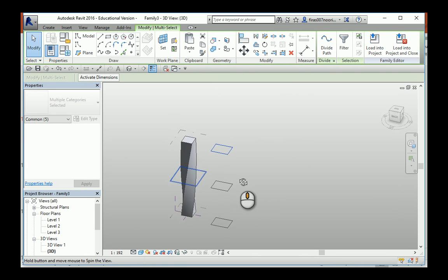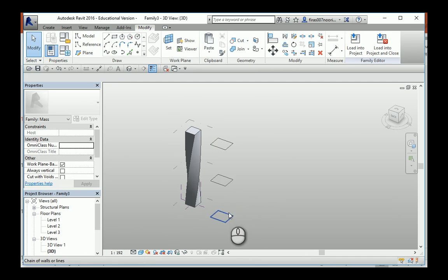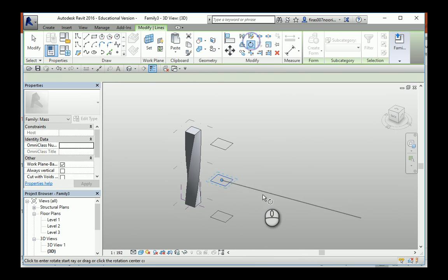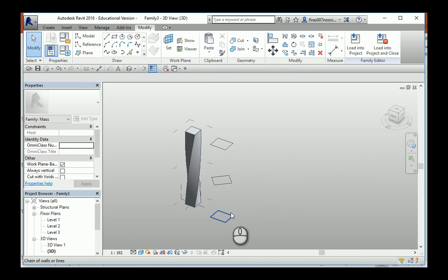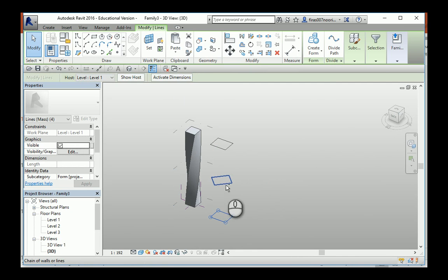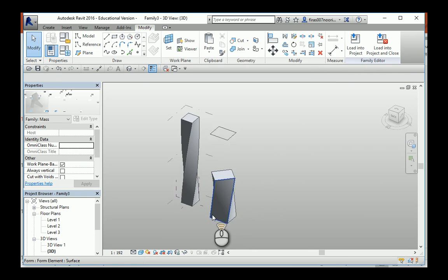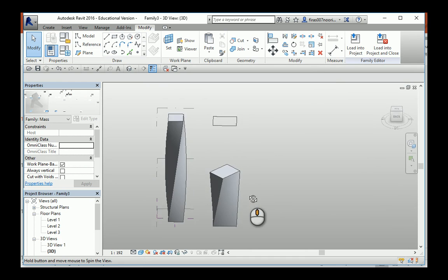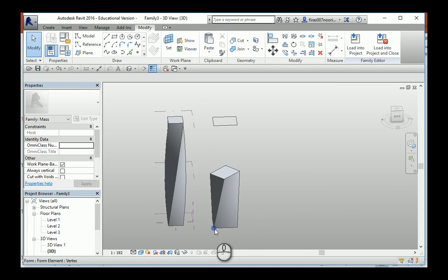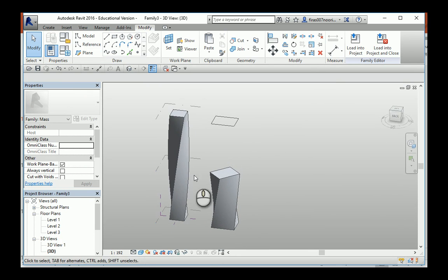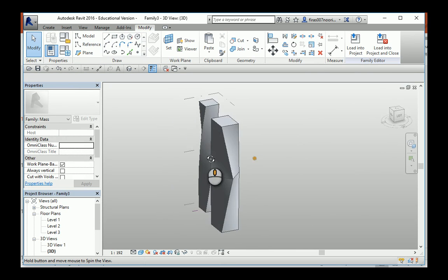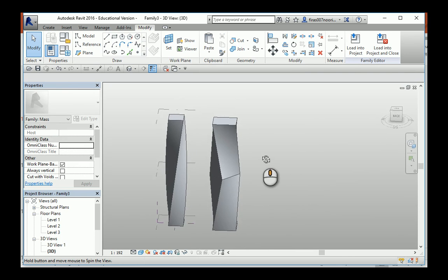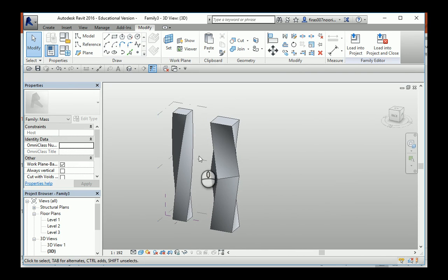Lots of mistakes, because some people just select this guy and then rotate it 45, you see, and that's the issue. Look, when you select this level and this level and then try to make them 3D, the actual result is a linear twist, not a curved twist like this. If you keep going and select those two things again and then select this solid, you get a totally different thing rather than what you are expecting.